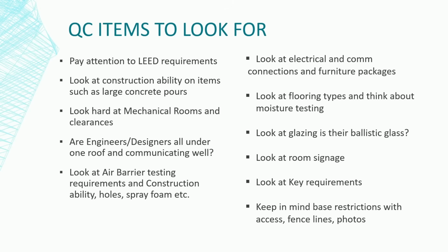Also, we did a 5-star resort there in the Colorado area. We did a lot of work for the Broadmoor, if you're familiar with the Broadmoor Hotel, and they love their exotic wood flooring. And a lot of that stuff has to be flown in, and then it needs to acclimate in the building for several weeks, sometimes a month or more before it can be laid. So pay attention to that when you're looking at the flooring type, because you're going to need to get those flooring submittals in and approved fast so that the procurement can go, so that the flooring can come and sit inside the building. So look at that.